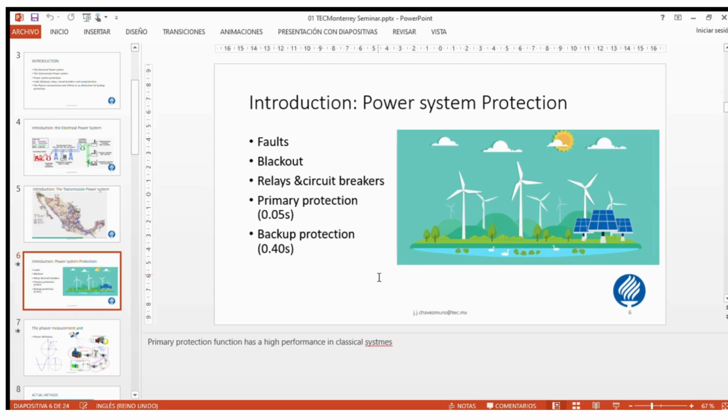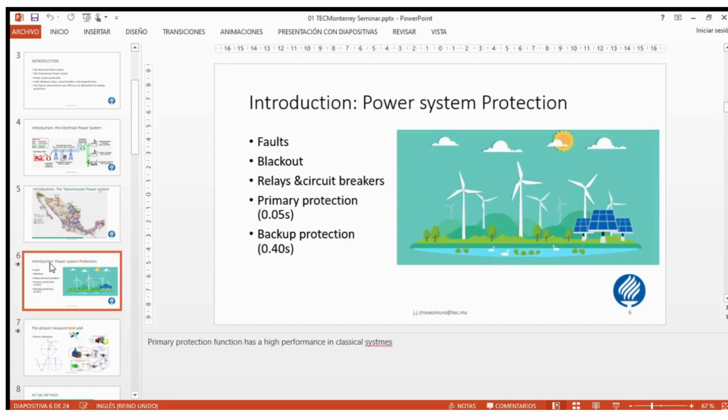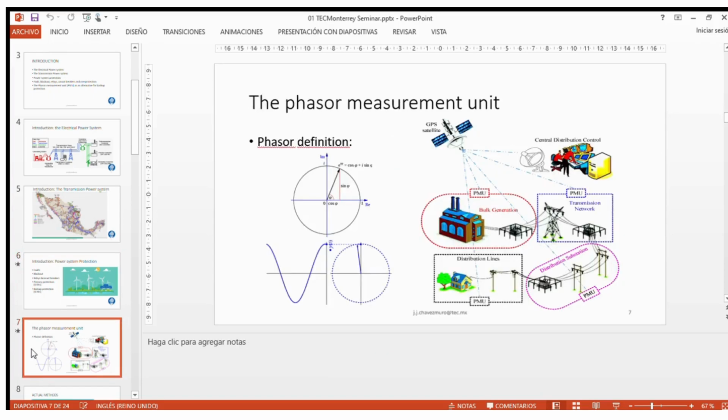Okay. So why don't we look for another element to protect the system, not a relay, another element, and with another methodology, because we are doing the backup protection most of the time with the same element and with the same methodology, but with different sensitivities. Okay, so we are proposing here to use the synchrophasor measurement unit. The synchrophasor measurement unit does two main tasks.